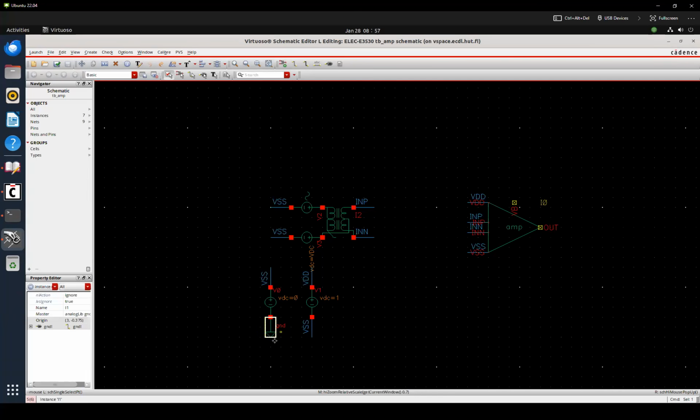This one is a ground, a global ground, that globally organizes the whole simulation world. If you just set a global ground for every single place, it may make some small mistakes. Is it required? It's good practice. It's not strictly required to do it this way. It's a good practice to avoid mistakes.